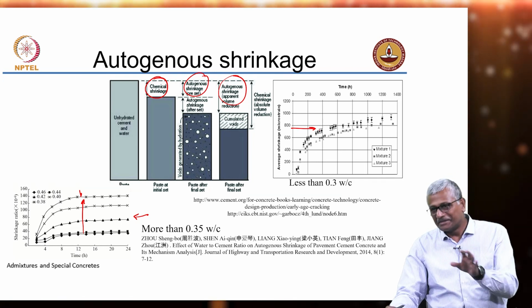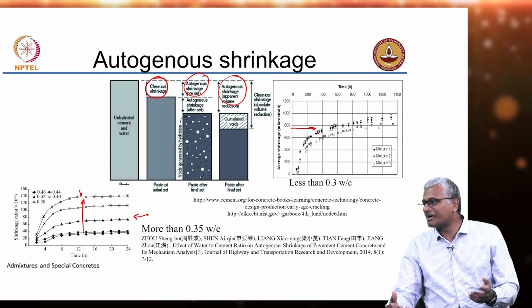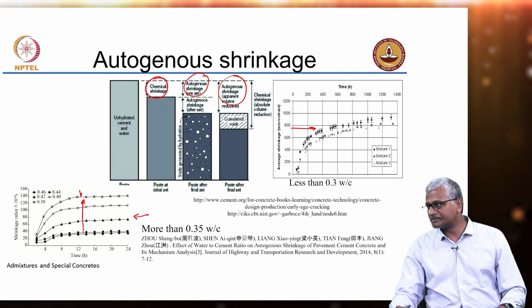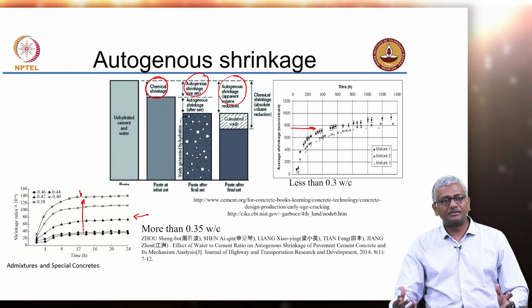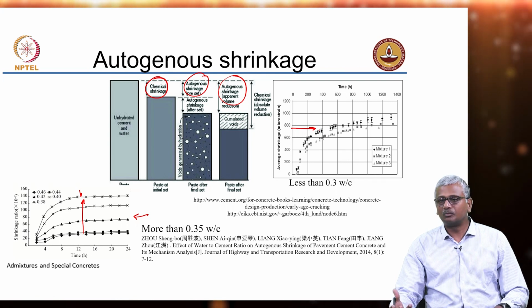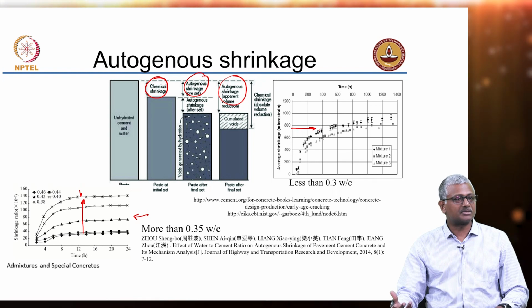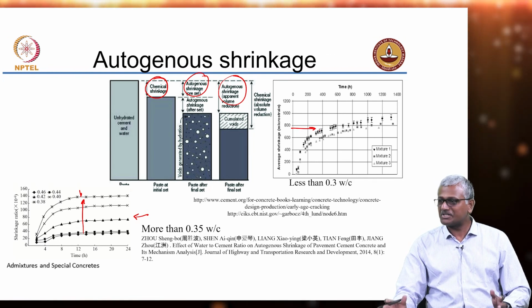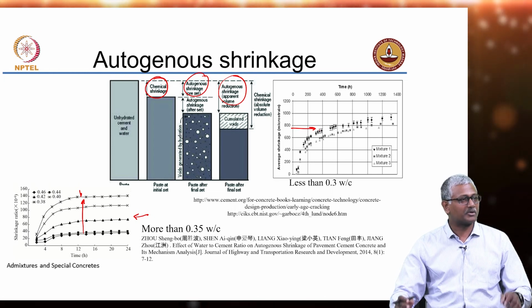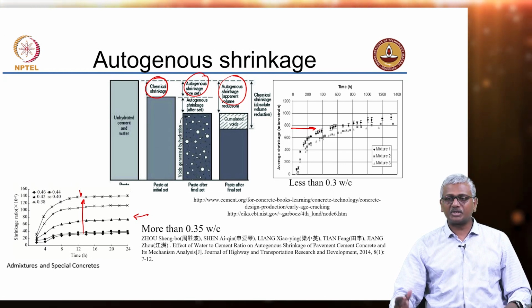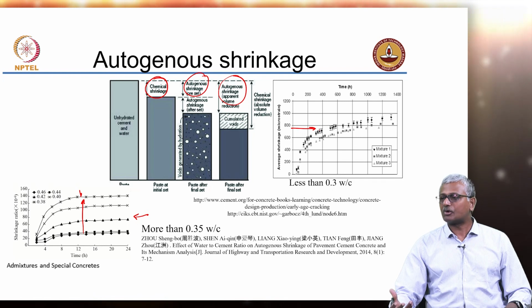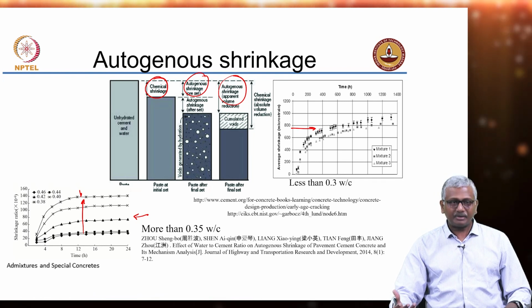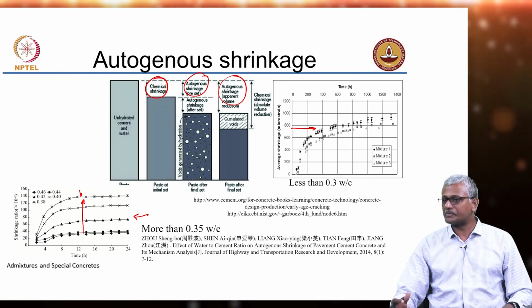Drying shrinkage, you can't prevent evaporation of water, it is going to eventually happen. You have to accommodate that through your design, right? What do you need to design for? What takes care of shrinkage? In a conventional concrete, let us forget about admixtures for now. How is shrinkage and thermal effects taken care of? Reinforcement, right? We provide reinforcement.